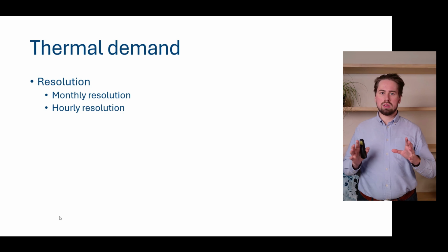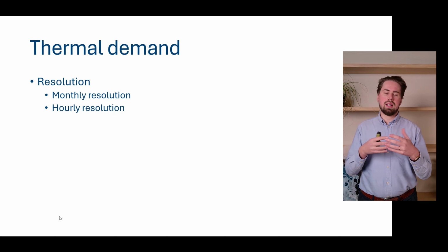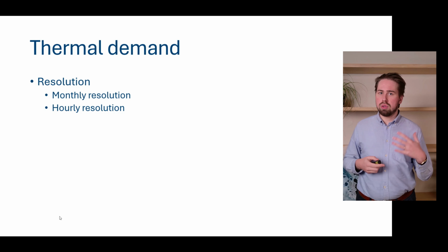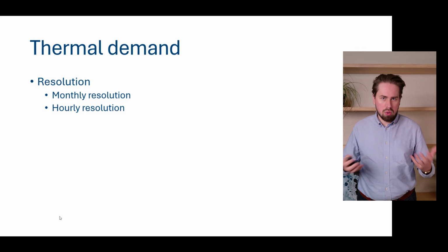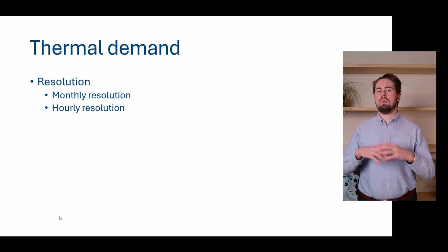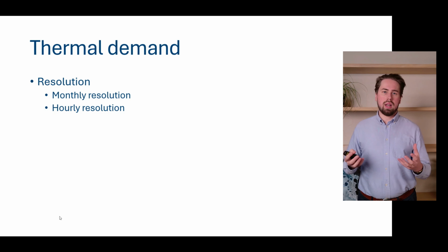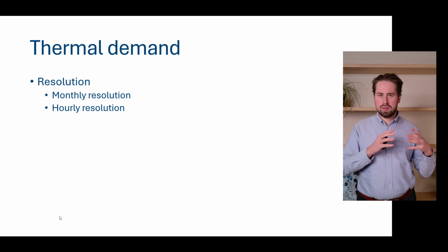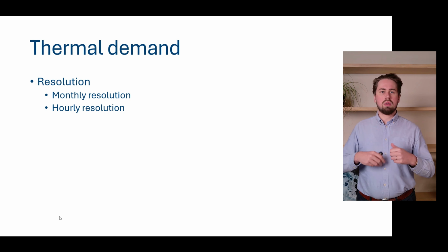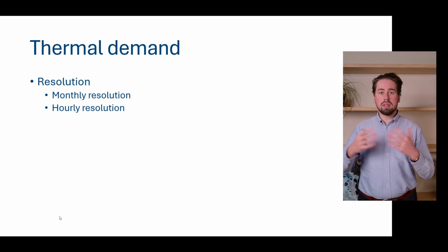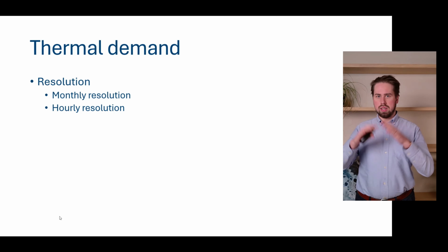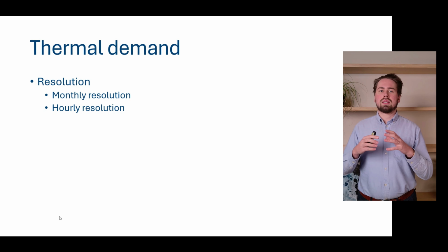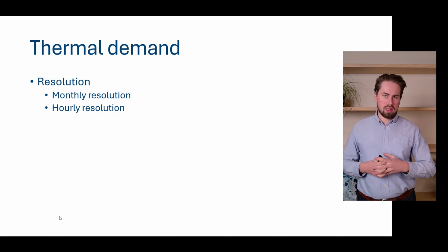So when we're talking about the building thermal demand, you can basically have it in two resolutions. One way, which is typically done for feasibility studies, or most projects basically, is you work with a monthly resolution, meaning that you have values for heating, cooling, and domestic hot water in every month of the simulation periods. Now, in GHG2 you can even work with yearly estimates, a yearly energy demand, which is then automatically spread out using a default profile. But that's the way you typically design bore fields.